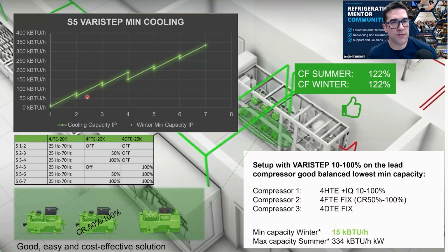Yeah, and this is going to be a balance for the manufacturer too, and the end user, because now 8 compressors cost way too much. You're not going to do that. And then with only 2 compressors, like you mentioned, if one fails, you don't get anything to help you out. But if you have 3 or 4 in between, if something happens, a valve plate damages or something, you still can keep the system going.